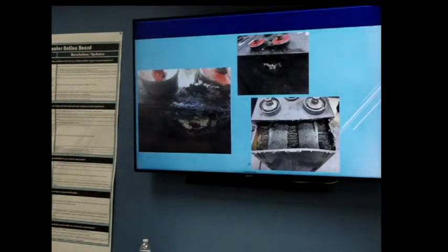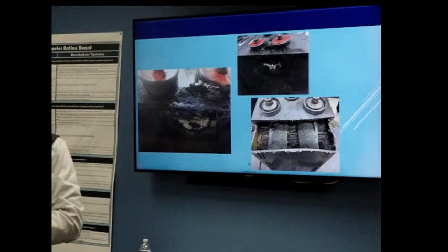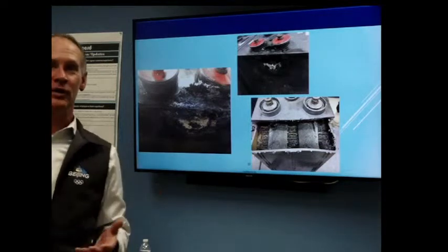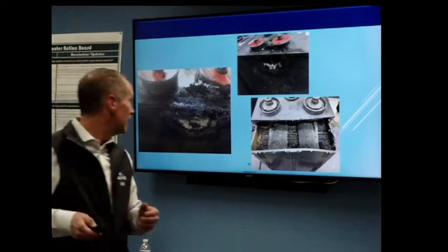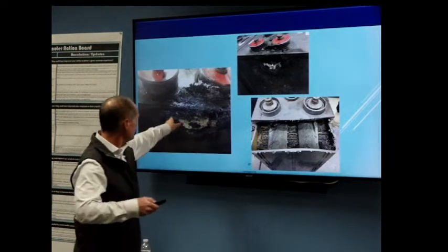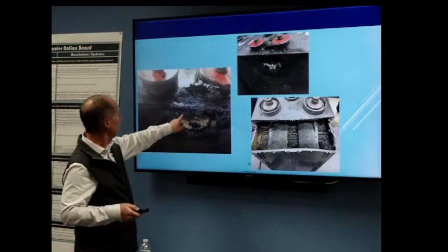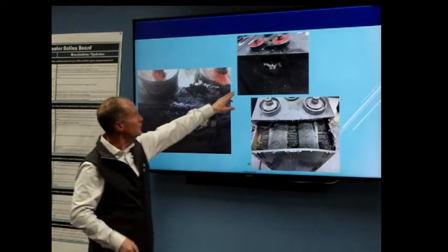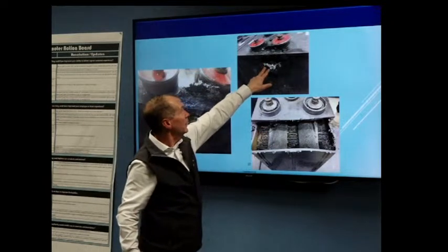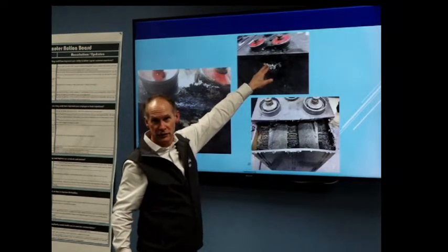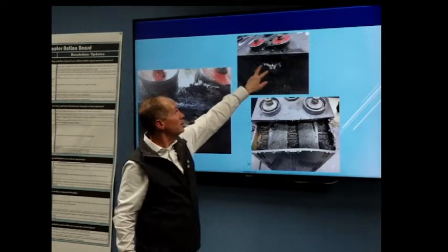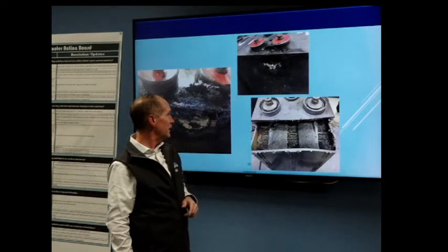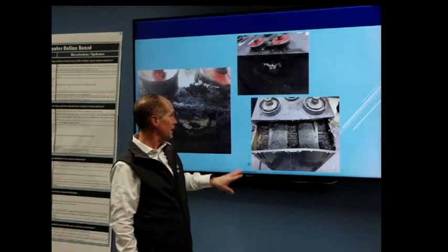And this is what we actually did to try to figure out what happened to the battery. We actually had to break the battery. We had to cut it apart. We had to do some sort of forensics to try to figure out what happened. And as you can see, where this melted out at the base of the battery where it made contact with metal, it generated a solid short. And that solid short, luckily it didn't take down the DC power plant, but it did cause a whole bunch of smoke and a lot of bad stuff to come in.